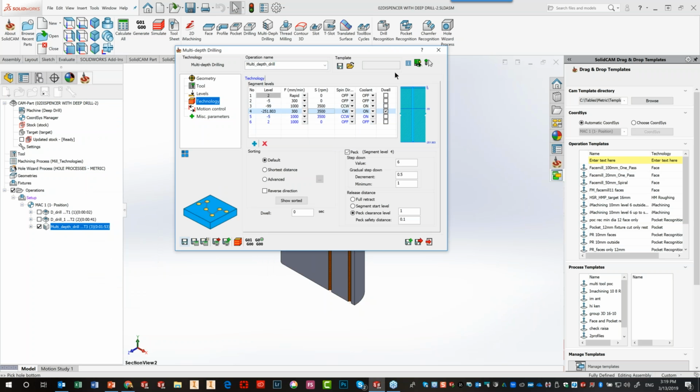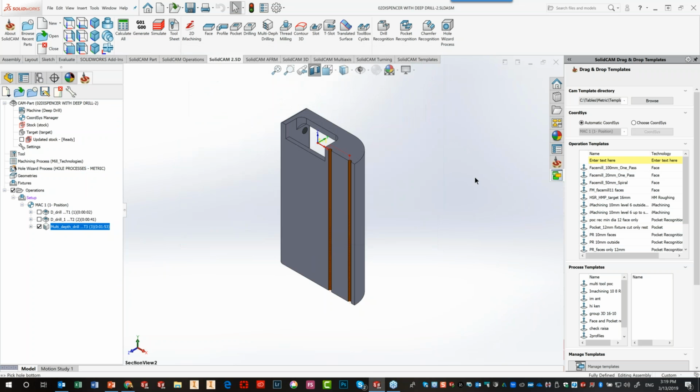Now, if you're asking about the G code on this, this is a non-cycle drilling operation. Your G code will be all linear movements, whether it be G1 or G0. Everything will be exactly according to those. There's no cycles in this at all. So it does not make a difference what machine you're on, because it's not using a cycle. It's just using regular linear code for this. Okay.